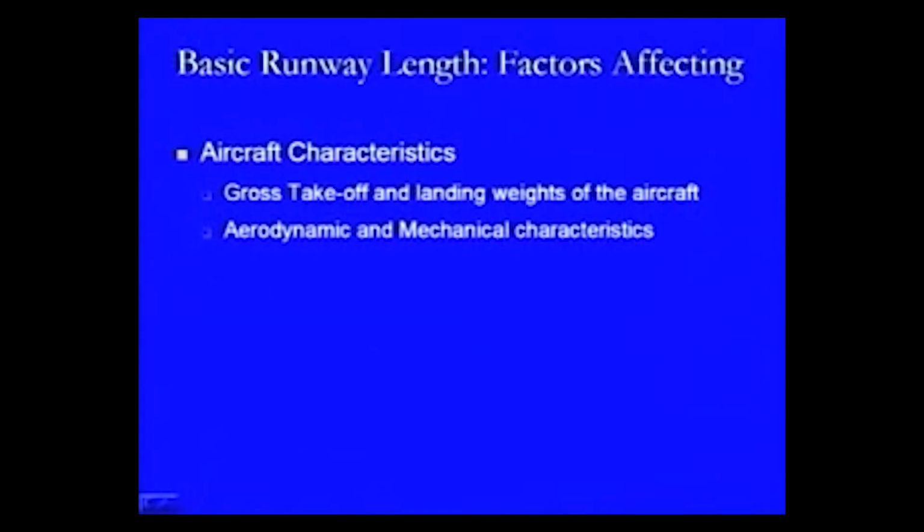So, that is the effect of the takeoff load for the aircraft, and in case of a runway length there will be more length required if there is a higher takeoff gross weight. In the case of the landing weight, this is another condition where we are looking at the effect of this weight, where it acts again in the downward direction, but then due to the effect of this weight, what we can see is that again there will be a change in the length of the runway strip because of the velocity with which it will be moving.